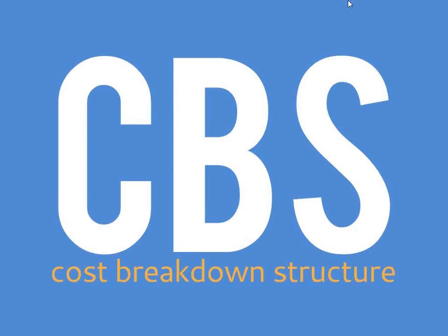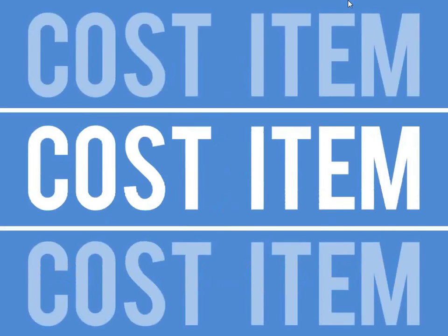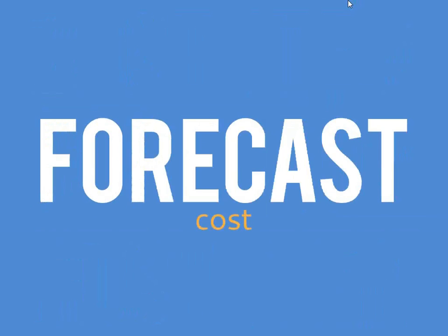In Hard Dollar's estimating product, we refer to the work breakdown structure as the cost breakdown structure, because this is where you'll create an outline of your project costs. Typically, the outline will break down into multiple levels of hierarchy with tasks and subtasks. The lower level tasks are going to roll up to their parent items using a bottoms-up estimating approach. Each task or activity that is created in the cost breakdown structure is referred to as a cost item in HD. So each cost item in HD represents an action item of work that needs to be accomplished. For example, pouring the concrete or excavating the trench.